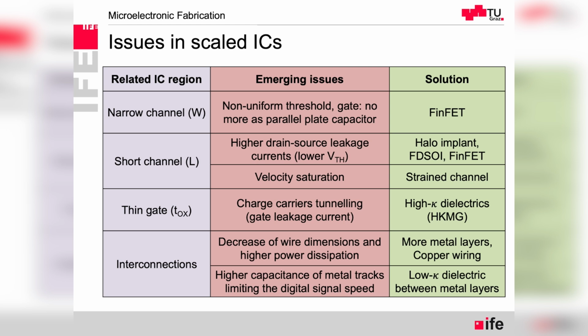decreasing, and also spacing is decreasing. So we have a higher resistance of the wire per unit length, if we want to take the minimum width of the wire. And also two wires are closer together, causing more capacitance between the two wires. Let's say if one is shielding to ground, we have capacitance to ground, but there could be cross-coupling between two signals, and that's also problematic.